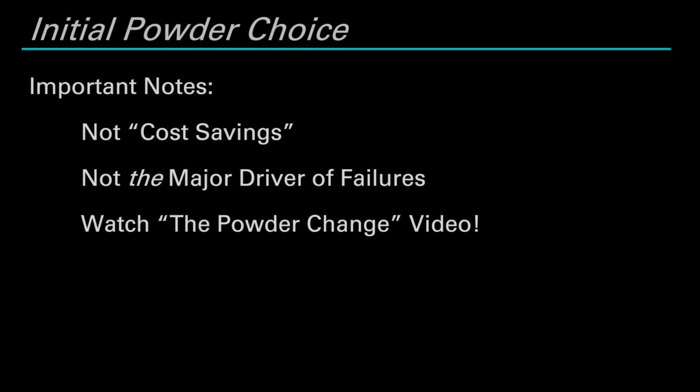Despite what the ICORD hearings and maybe other presentations on this topic will lead you to believe, the powder was not the major driver of failures. While it did expose the inadequacy of the buffer design, and it did cause parts in the guns to break prematurely, and those parts had to be reinforced, by the time the new buffer was implemented in 1966, and the time that retrofit was complete in 1967, the powder issue was more or less resolved as it came to an increase in rate of fire.